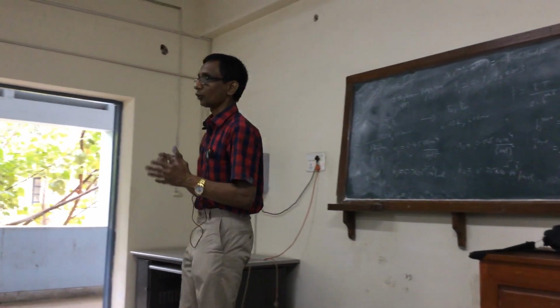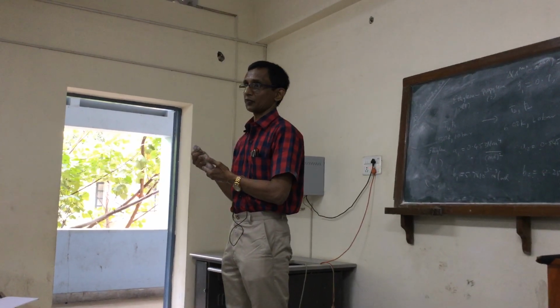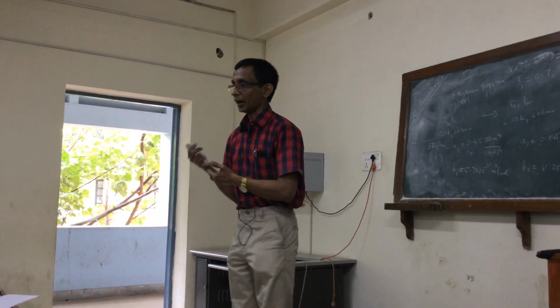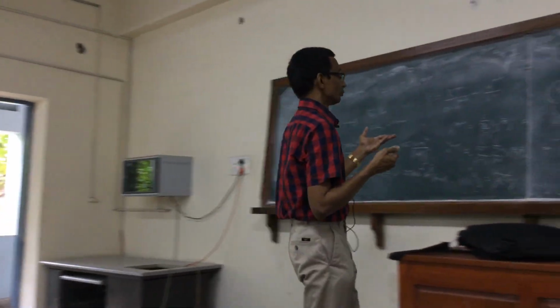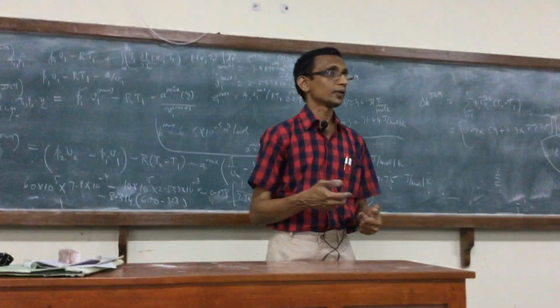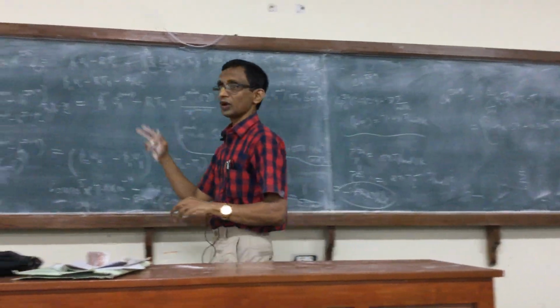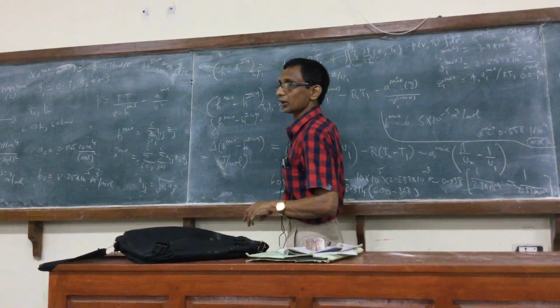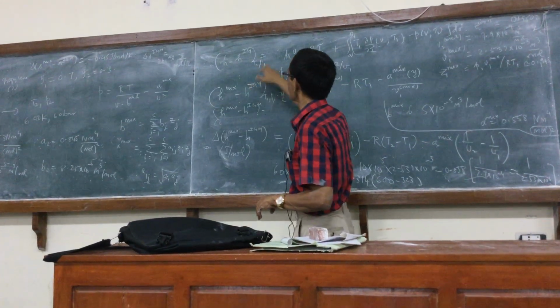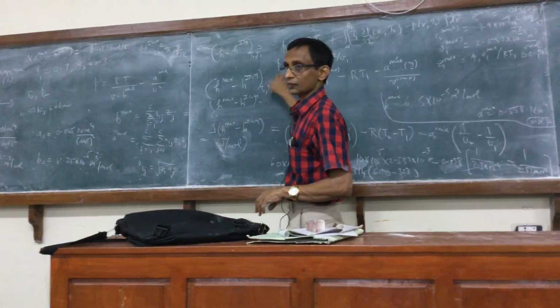But we have also seen how to calculate the properties of the mixture from the equation of state, right? And the procedure is the same, how to infer the formula for the mixture calculation from the corresponding formula for the pure compound. So what I will do is go to the formula for S minus S IG, get what this is for the Van der Waals.